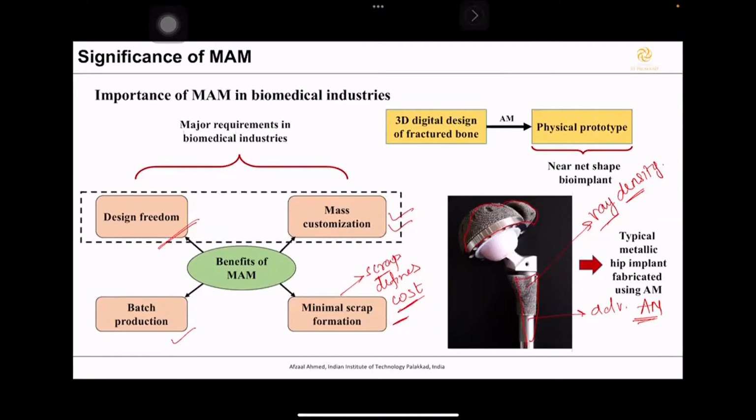The other thing is that the abrasives may get stuck to the internal surface, and that again forms irregularity on the surface. And if you talk about dimensions, let's say you need a 40 or 80 micron internal hole, then the slurry or abrasive particle size is in that range, so you cannot use that. You have to use some other process for such internal features. So there is a need now, and it is a good thing for people to think about how to make a process for this.